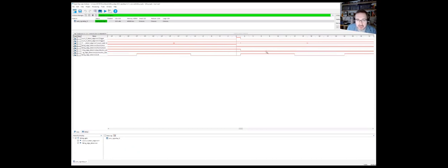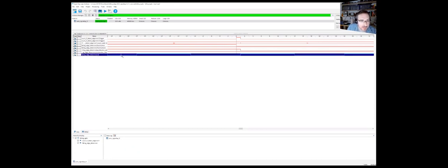If I just zoom out a bit, actually, this bottom one is the clock, and the trigger, you can see, is significantly narrower than the clock period, and that's not good for the upstream logic. I'm going to press it again. That one is bigger. So we've got lucky with that one. That's a fairly wide pulse. Try again. Again, another wide one. And I'm going to keep on pressing it so you can see the variability.